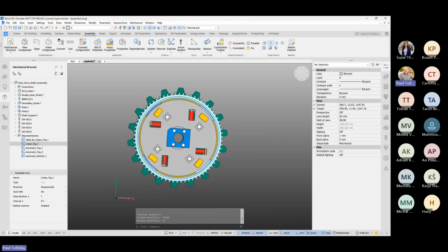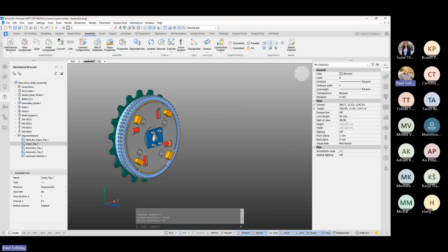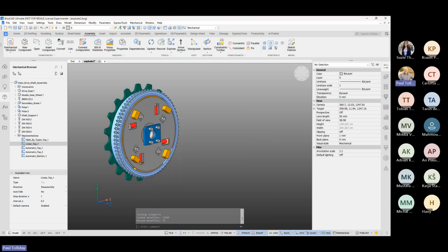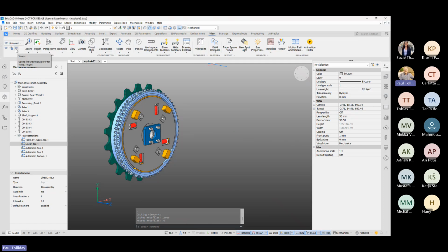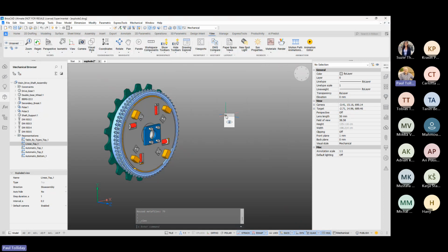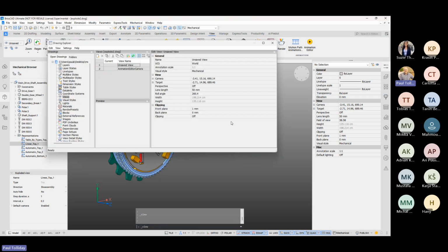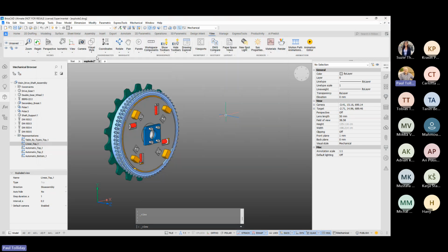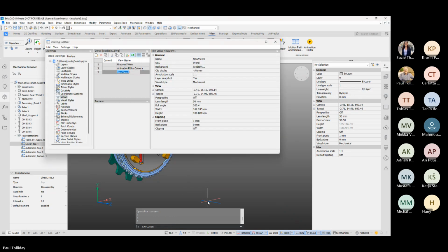Very, very simply. What we can do is move the object or the assembly to the view that we want to use. We can then either go to our View tab, and here we have Views. So we can select that, and you've got all of your views that you're going to use. Or you can simply right click in open space, and we've got our view control there as well. So if I now open this and I create a new view, the window that I've got selected, and I'm going to give it a name of ISO 1.